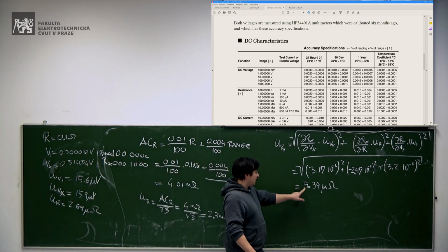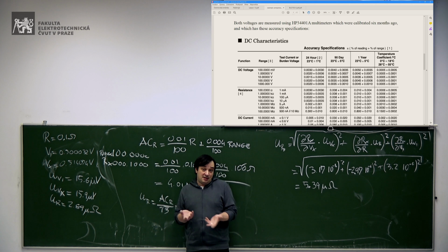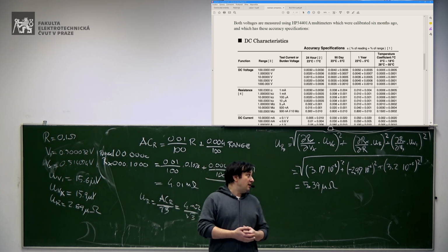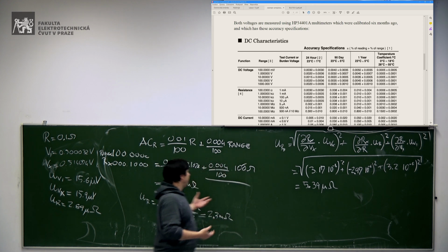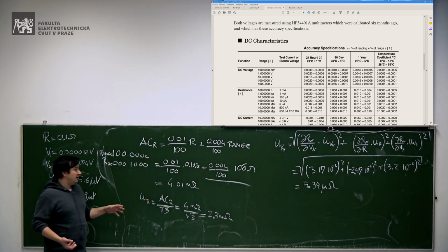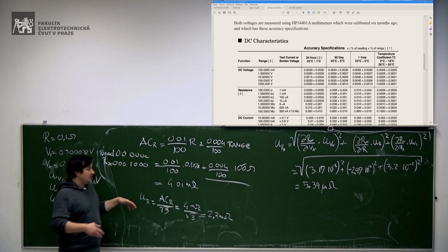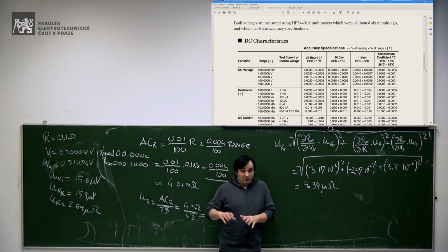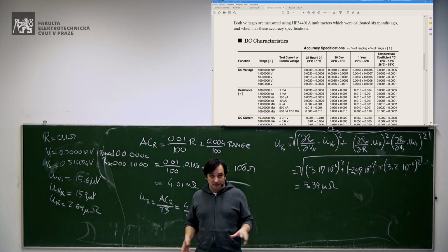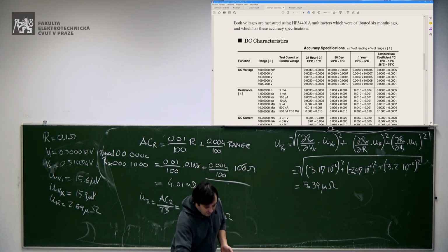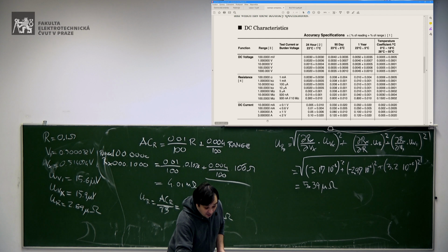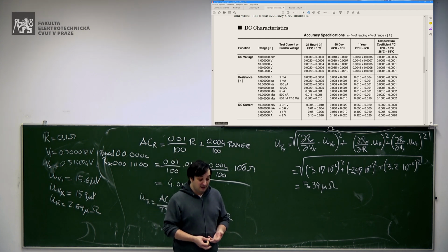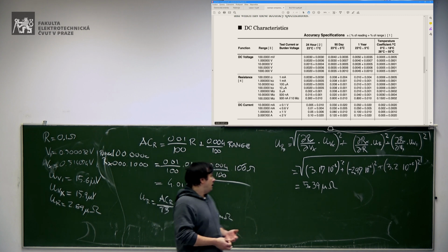Here you have an uncertainty much lower, 3 orders of magnitude lower, simply because, you remember, you can use 2 of these multimeters and use a larger current, about 5 amperes. You don't have to measure the current, so you don't care about measuring the current, which could be complicated. For instance, here, at most, you arrive to 3 amperes, so you cannot measure directly 5 amperes, okay?